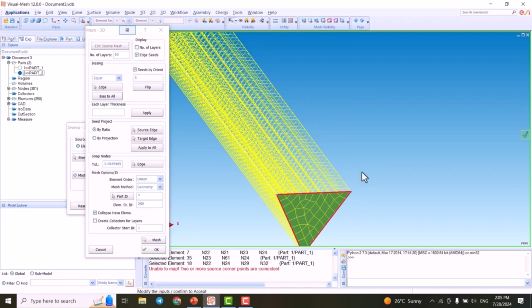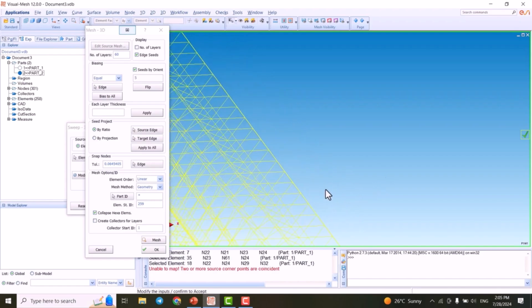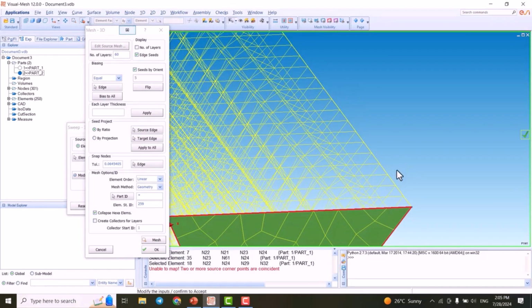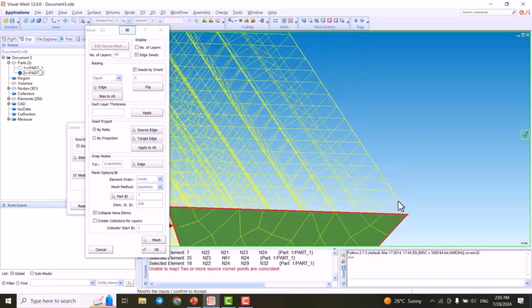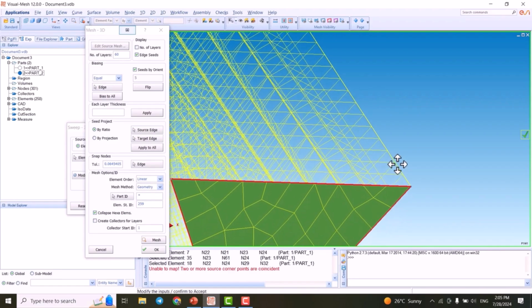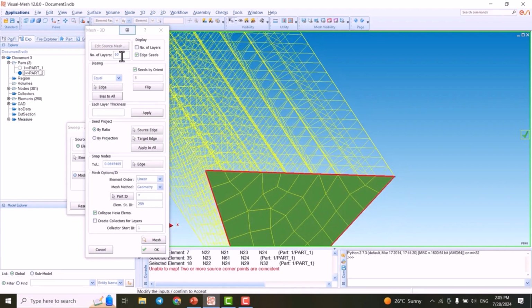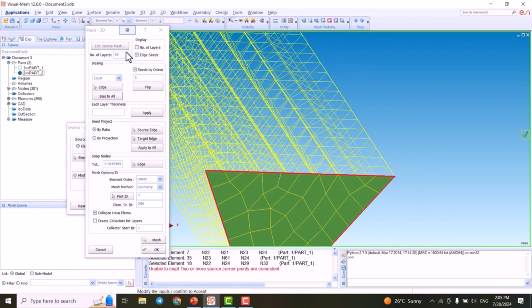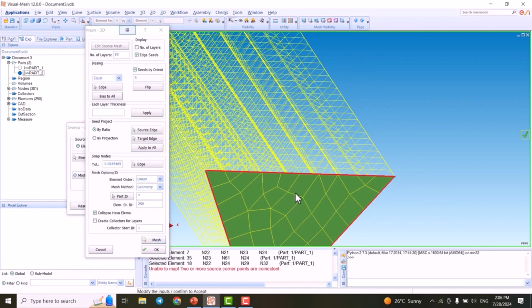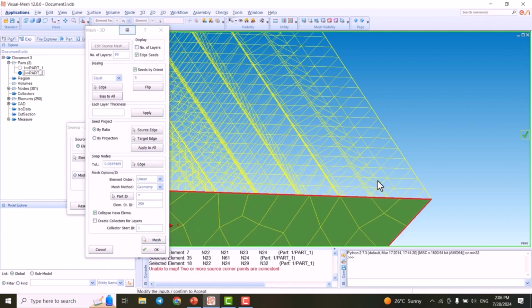We cannot see that actually, but you can kind of see whether the model is in your favor or not. Let's modify this. If we want it to be smaller, we can make this, for instance, 90, and we see how our mesh is going to be.